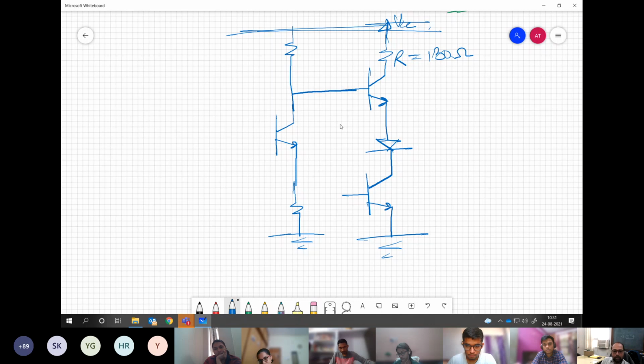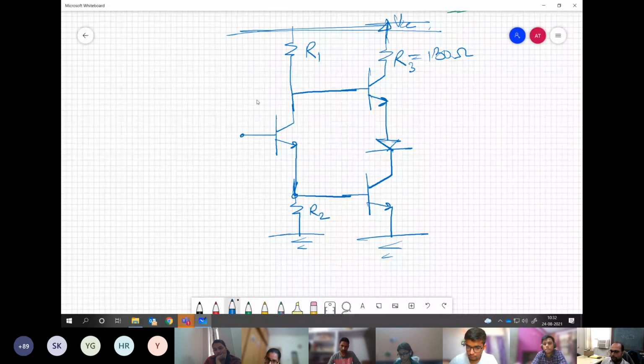So you can connect this terminal over here and this terminal over here. So let's say R1 and R2. See, these R1, R2 are the things we will be changing, depending on when we go to the full circuit or we include more components. So this count you don't try to remember, only try to remember the configuration. Now this R1 is of the order of 1.6 kilo ohm, that is the standard TTL value that is considered, and this is something like 1 kilo ohm.